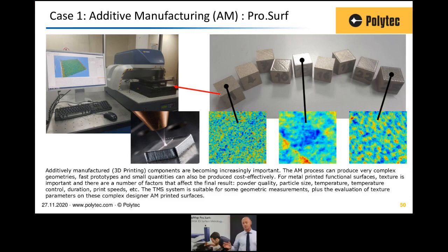Additive manufacturing is very popular. This particular example set is from the ProSurf as measured. People are typically sticking 20 micron spheres onto a surface and melting them. If you consider the XY performance of the ProSurf, optically it is from 8.4 microns, and pixel to pixel sampling is from 14. So you have a pretty good match for the smallest things you may want to measure.